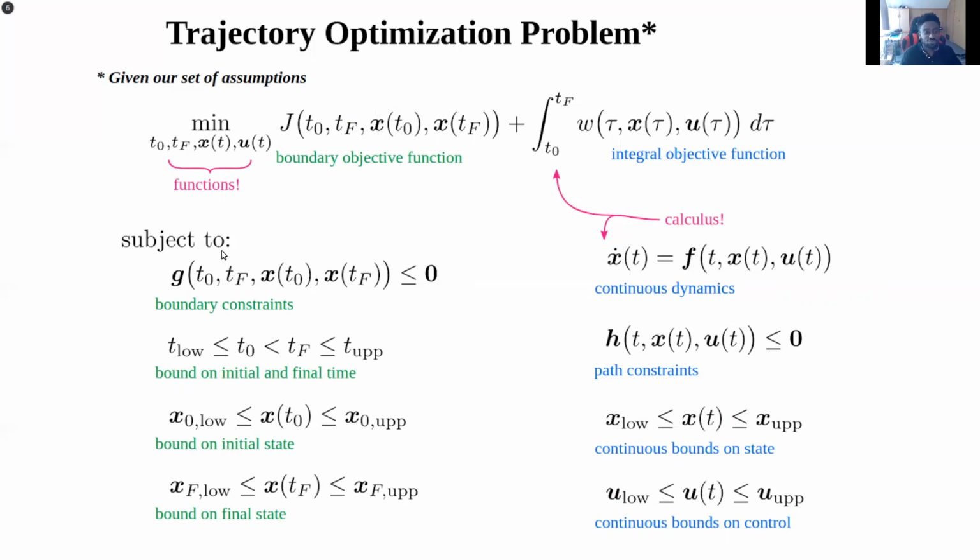And constraints are usually ways we are able to impose our preferences on the optimization algorithm in order to come up with solutions for us. So the goal of this trajectory optimization problem is to come up with these control variables. That's basically the states and actions, because a trajectory is just made up of states and actions. So all you want is to come up with a trajectory that's made up of optimal states and actions, where a state at time t is continuous, and because they're continuous, they have this bracket and t.